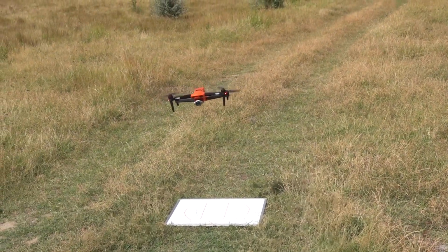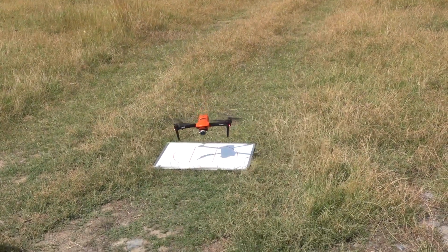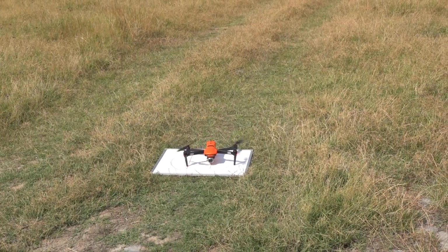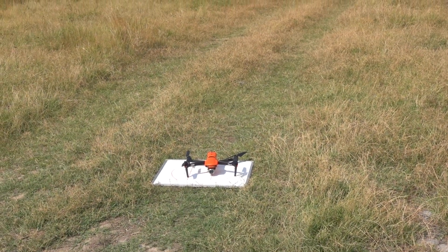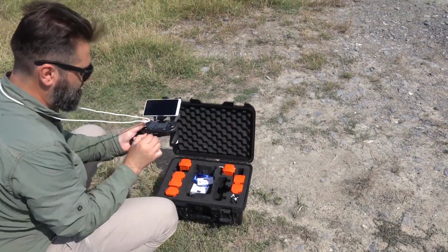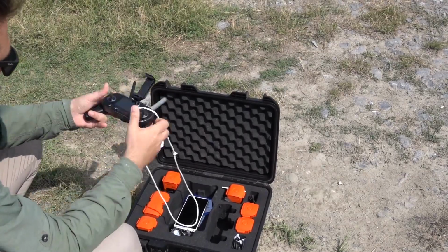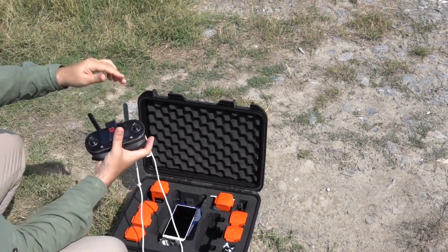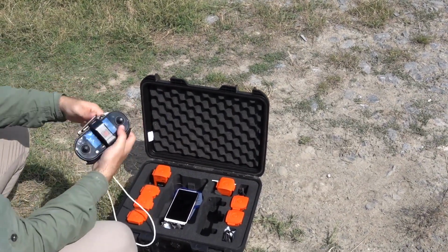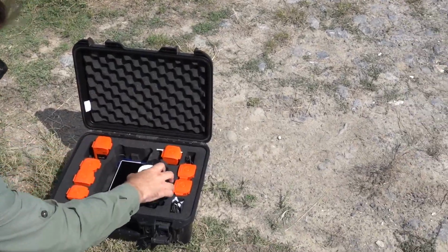When the survey is finished, the drone will automatically land from where it started, with no user intervention needed otherwise. With the drone landed, switch off the remote controller and the drone's battery, and begin packing up tidily and with caution. Make sure to let the drone's battery cool down during packing.